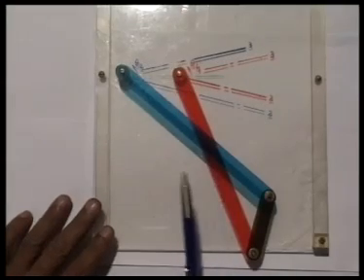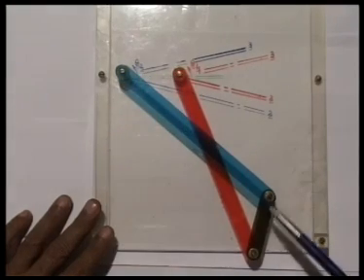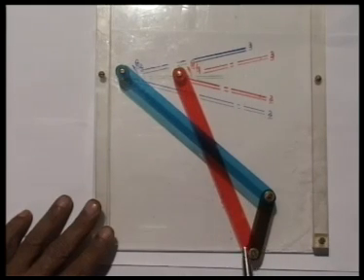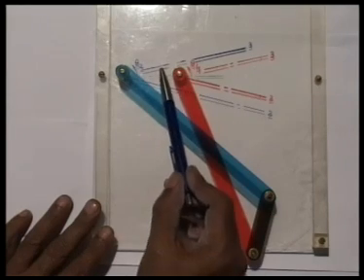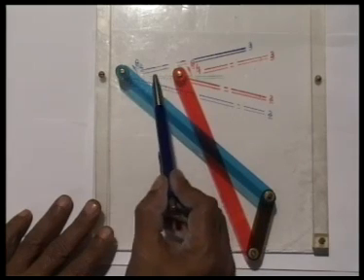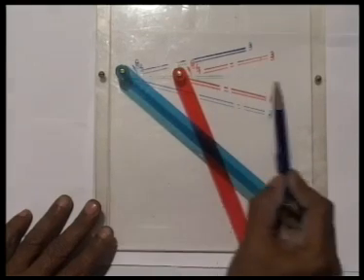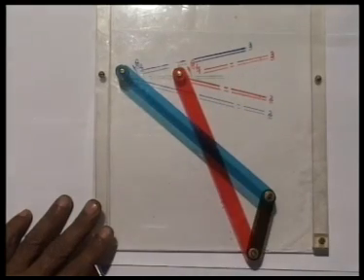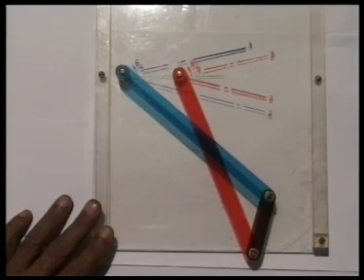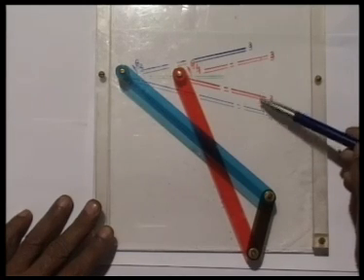This is the model that we have got. This L1 is 5.1 centimeter and L1 is equal to the coupler length L3, and L2 is also equal to the follower length L4. This is the first configuration where theta 2 1, that is angle that this link makes with O2O4, that is minus 40 degree, whereas the angle that this follower makes with the same line O2O4 is minus 68 degree. So, this configuration is taken up by this anti-parallelogram assembly, whereas the second position, which is minus 14 degree for both, is these two configurations.